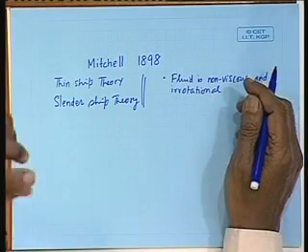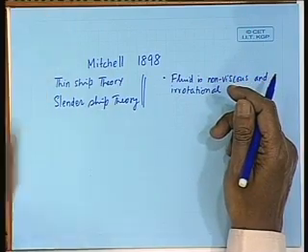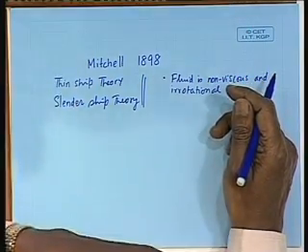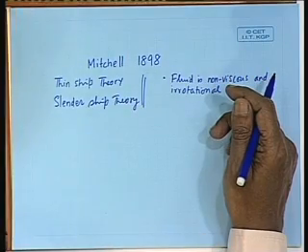Irrotational means the fluid particles do not have a rotational component of velocity. All velocities are linear. What does that mean? Where does the fluid particle have a rotational velocity? Can you tell me? Yes, a vortex, which need not be in the boundary layer, which can happen in a non-viscous fluid. That vortex or circulation, that is rotational flow.